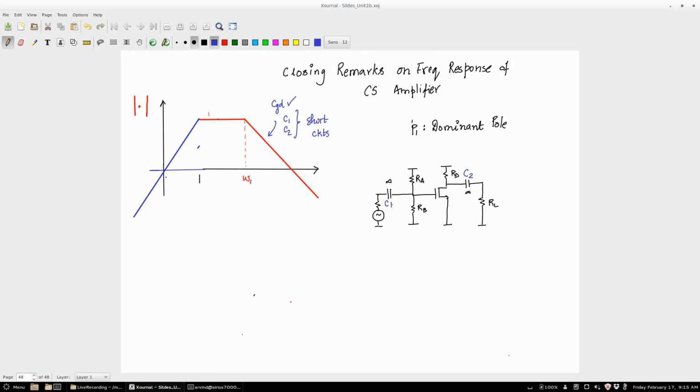So I am going to attach it here. Basically, when I moved it, this is 20 dB per decade, right? This red line. The blue line also is 20 dB per decade. And I drew this frequency to look like omega equal to 0. That's all. But this is a log scale, so this actually will not be 0. You can never plot 0 on a log scale, right? So this is some very small frequency, so 0.0001, say. It's close to 0 but not 0. Right?